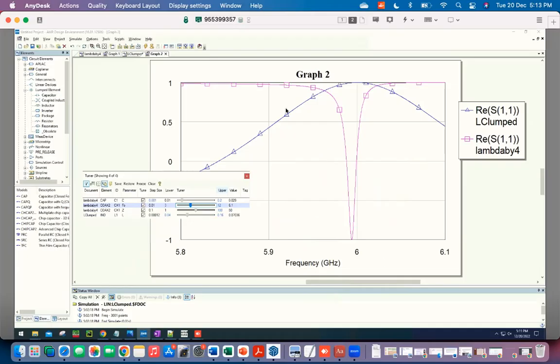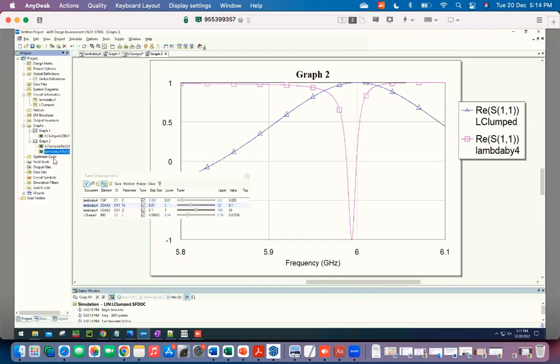So, and then finally the phase change is just because the capacitance is giving an extra reflection coefficient of the opposite sign. That doesn't really change anything about whether it's a parallel LC. It's still a parallel LC oscillator. Just there's an overall phase shift that has no consequence because you can always add a negative sign. So which also means that if I look at this thing in phase, you will see it will look different.